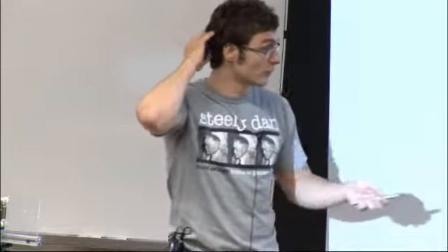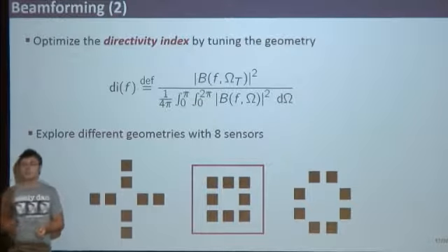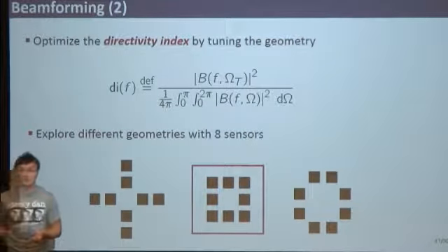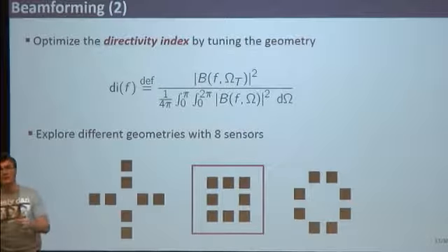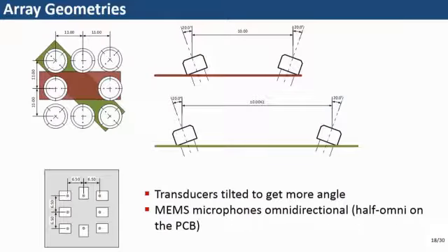It turns out that for the microphone array, the best overall geometry was this square one, and the spacing between the microphones that we use is 6.5 millimeters, which is slightly more than lambda half, than half of the wavelength. Okay, so this is the finalized geometry.